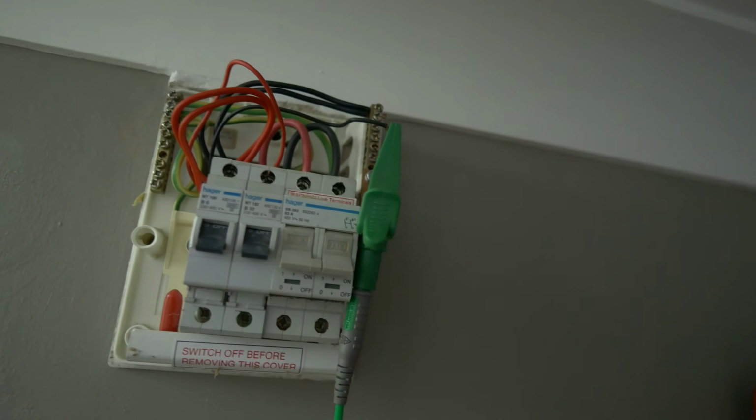That's sort of what you'd expect to see. Now, I'm not going to ramp that up to 500 volts because I am aware of the electronics in circuit. I don't want to cause an issue. We're above our 2 megaohms, so I'm happy with that and an understanding of why those results are presenting in the way that they are. So that's our insulation resistance testing on the socket circuit and on the lighting circuit.